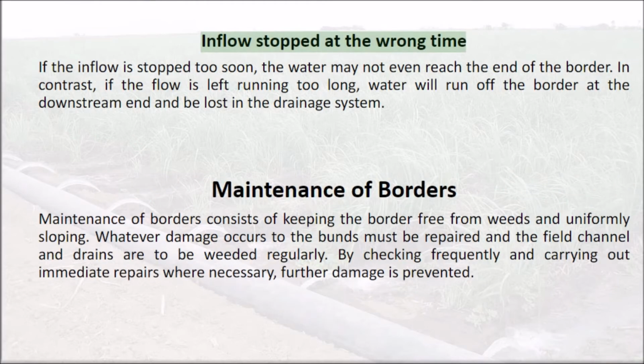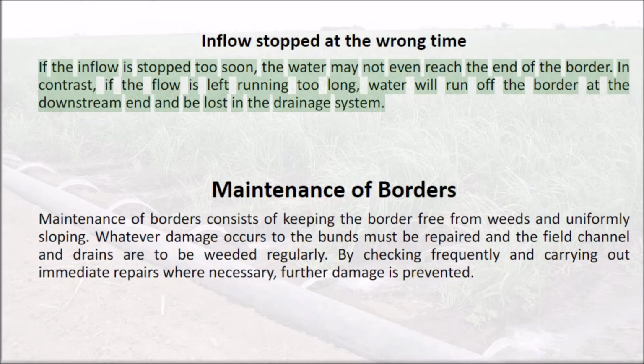Inflow stopped at the wrong time. If the inflow is stopped too soon, the water may not even reach the end of the border. In contrast, if the flow is left running too long, water will run off the border at the downstream end and be lost in the drainage system.